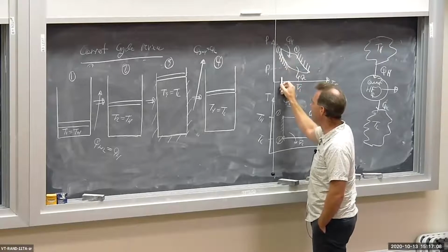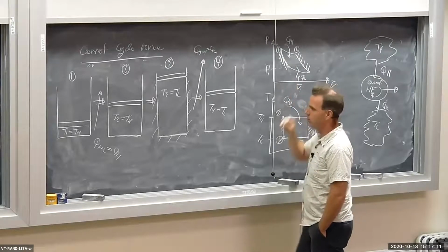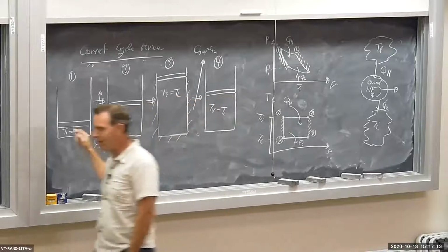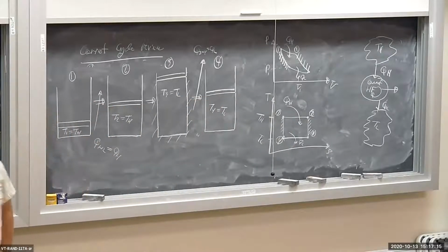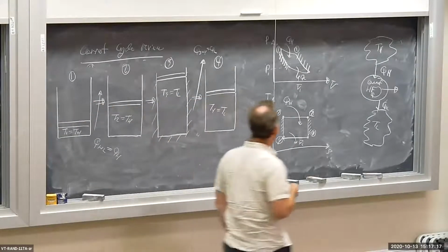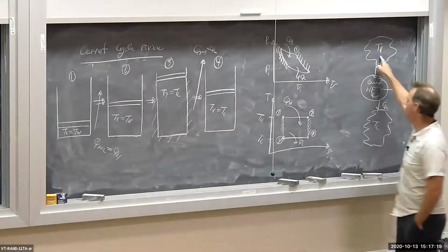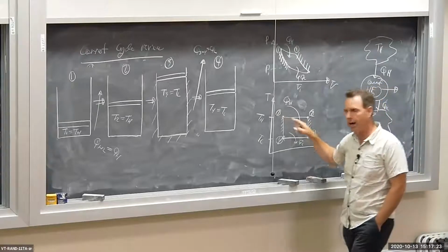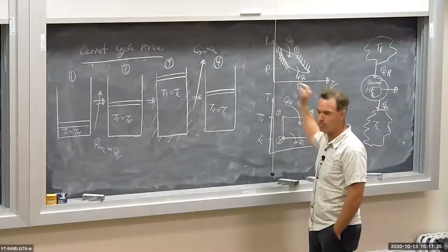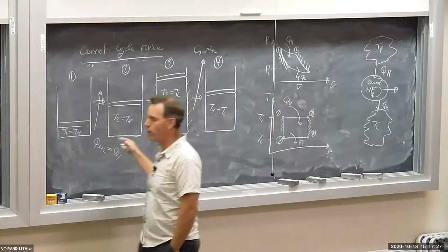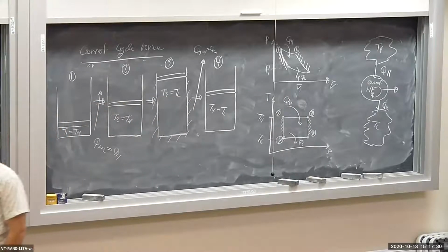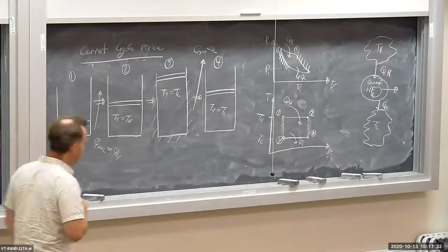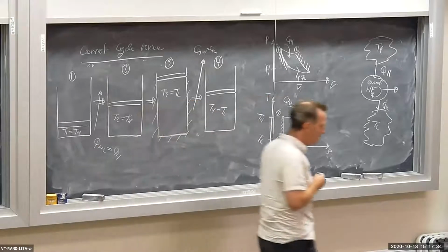Maximum pressure and minimum volume point. So state 1 is where we squeeze the gas down. State 1 is at the high temperature reservoir temperature TH. So at state 1, we're at temperature T high and we are at the minimum volume. And then we proceed to expand isothermally the gas in our piston cylinder device, and we do it reversibly.